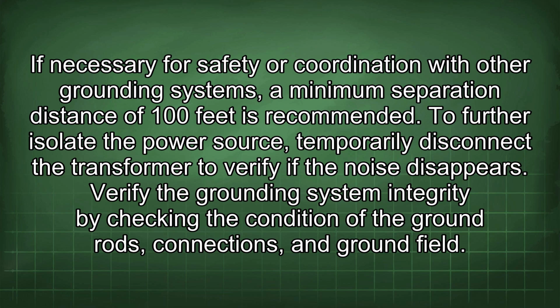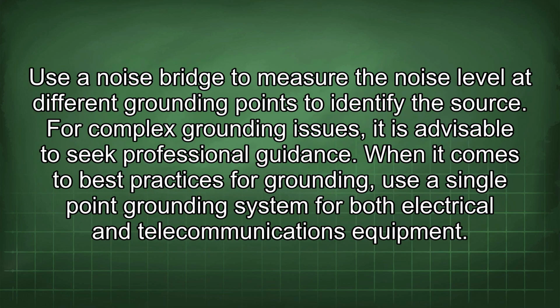Verify the grounding system integrity by checking the condition of the ground rods, connections, and ground field. Use a noise bridge to measure the noise level at different grounding points to identify the source. For complex grounding issues, it is advisable to seek professional guidance.